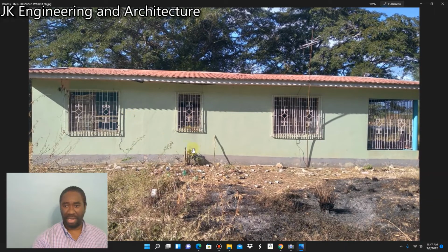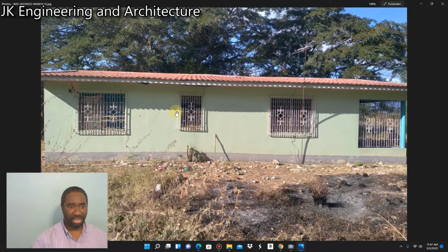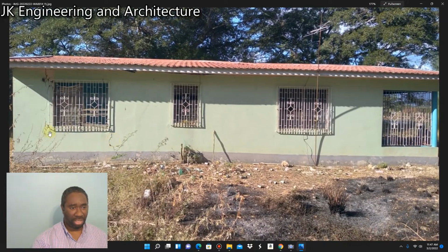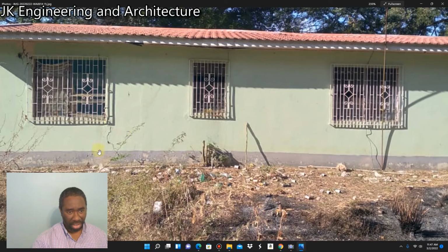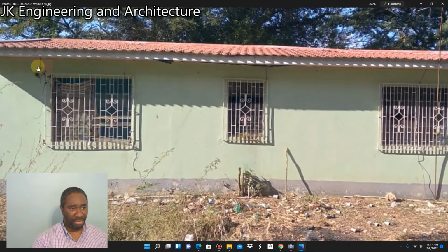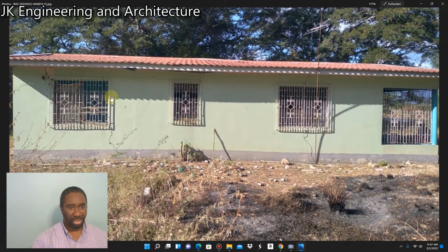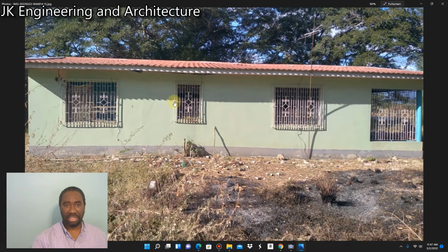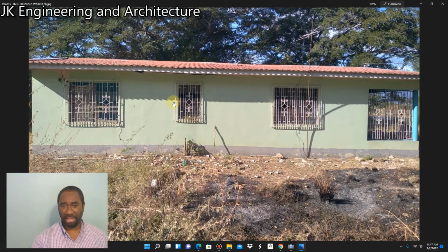This side, however, is not as bad as the other side. We are going to take out this piece of wall here. As you can see, there is another shear crack right here below the window, and I think one above the window. So we're going to take out this corner, take out that corner, and put a vertical stiffener column in them. But this side is pretty much better than the other side.